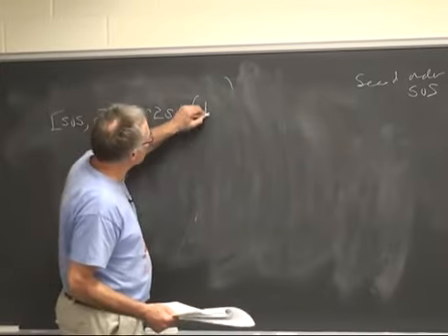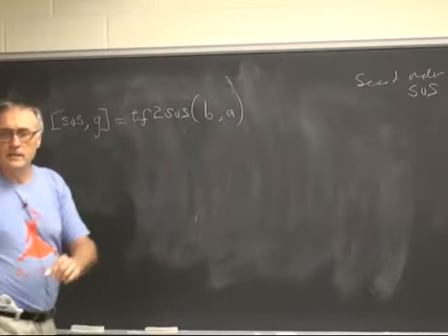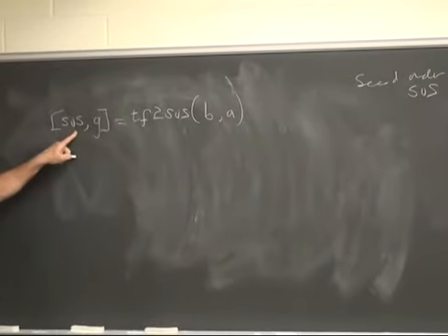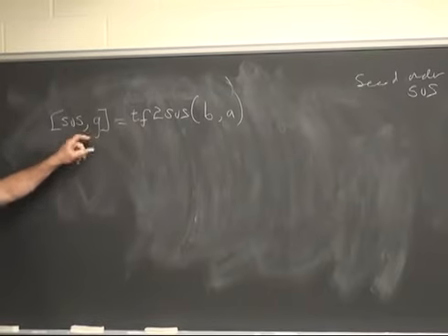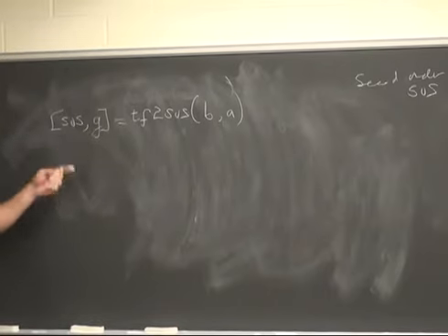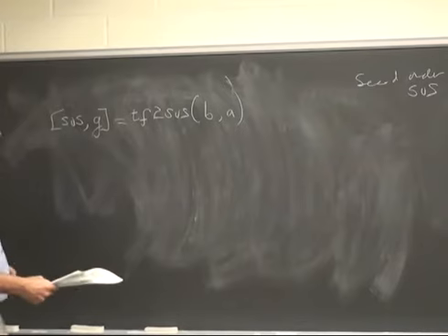You feed it a vector of B's and a vector of A's, and it calculates two structures for you. It calculates a matrix of second-order sections, and it calculates a gain that has to be multiplied by the result of the second-order sections.